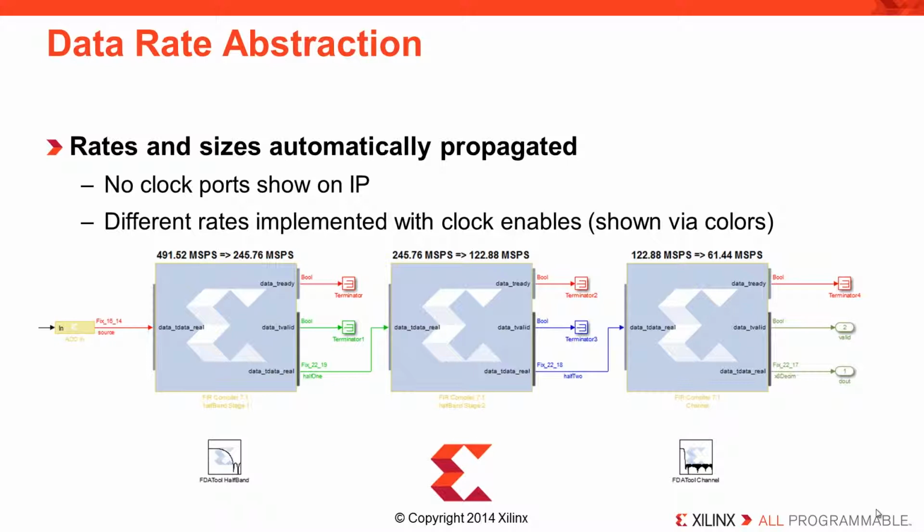The data is sampled at gateways into the block diagram, and that sample time is inherited to downstream blocks automatically. So when the data is upsampled to a higher rate, the new rate will propagate to the blocks it serves. This allows a large DSP system to be simulated as a model-based design, and then automatically converted into RTL to be added as blocks within the Vivado IP catalog.